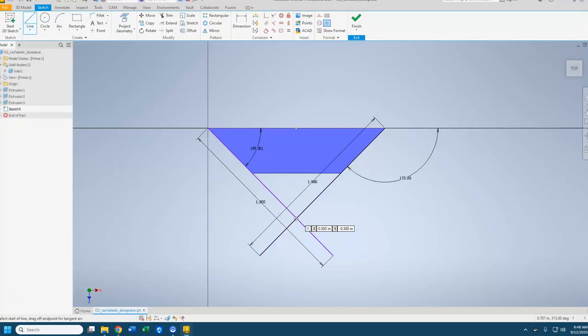So then we're going to take this intersection and click on it because we want to form a line that's 45 degrees from there. So it does look like I should, or sorry, not 45 degrees, 60 degrees. So it looks like it's going to let me type 60.